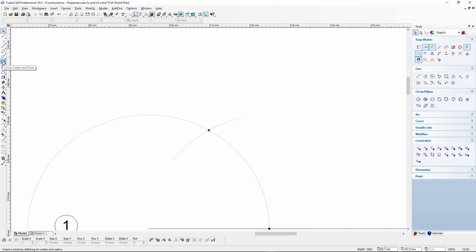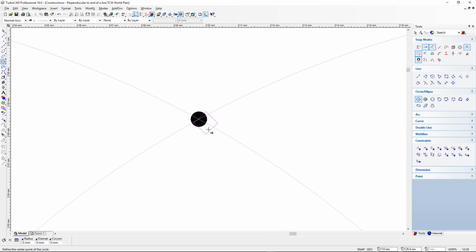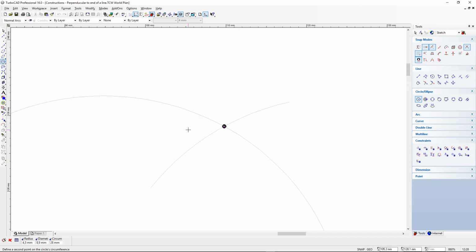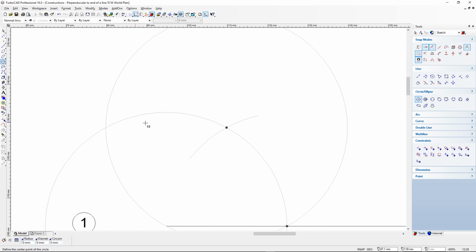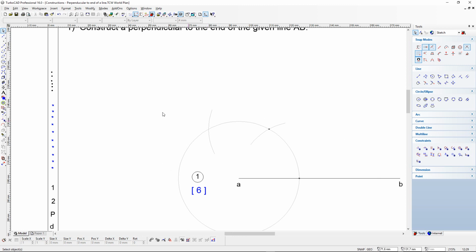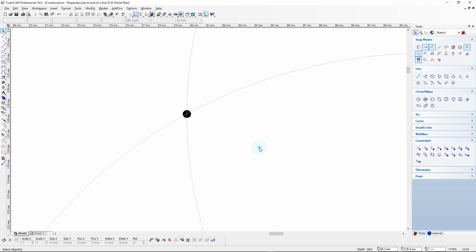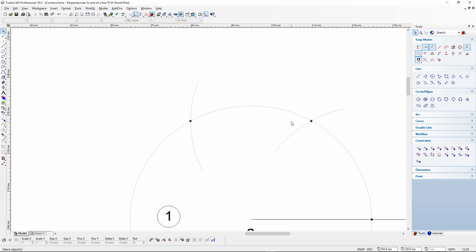I'm going to continue now by drawing from that second reference point another circle with a radius of 30 millimeters, and that will be cutting into the main circle that I've started my drawing with. And once again, I don't need the full construction circle, I only need to draw this section of the arc. If you are drawing on paper, you can also just draw that small piece of the arc as indicated here. And once again, we have a third reference point, and I'm going to draw a light little dot right there at the intersection between the main circle and the construction arc.